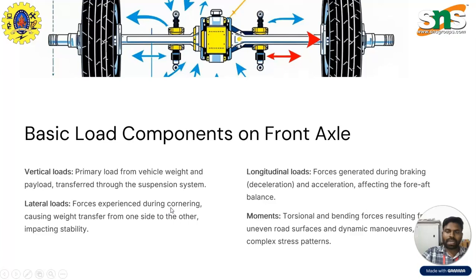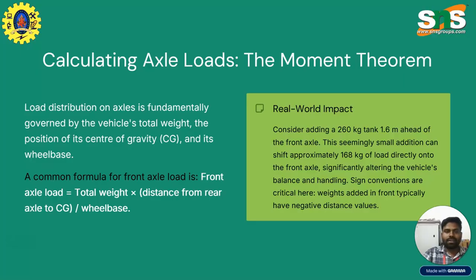Yes, if you make the vehicle turn, some amount of external forces act, so the vehicle front axle should resist these two loads, vertical and lateral loads, and the longitudinal load. Some amount of moment also acts on the front axle, so we can design the vehicle front axle while considering these factors: loads, moments, and stresses, and calculating axle loads.